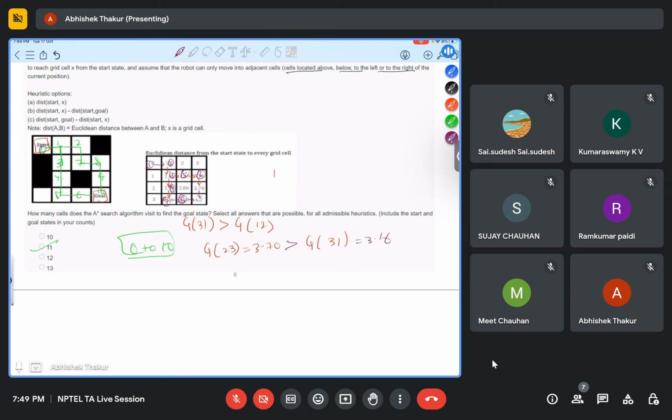So it will see what is the cost incurred, and after that it will move to the next cell. Let's suppose there are two paths. The final cost is given by F only. If the cost in path 2 is greater than path 1, then it will again follow path 1 to the goal. If it is less than path 1, then it will follow path 2 through the goal. Like this, we'll choose the lesser cost path.